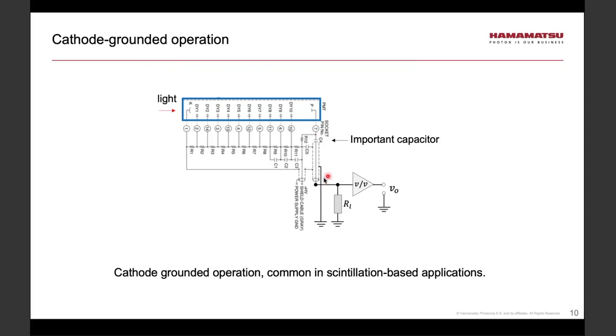To employ detection electronics, it is important to have a so-called coupling capacitor in this circuit, C4, which separates the very high potential at the anode from the electronics. Please note that this cathode grounded operation can only be used for pulsed or AC input light. One should not use it for DC.